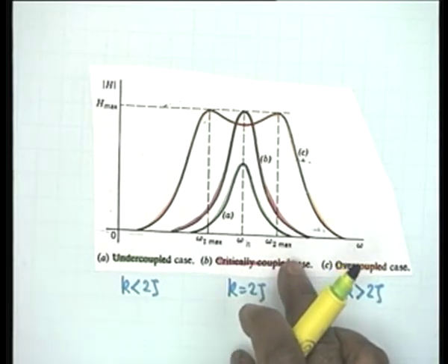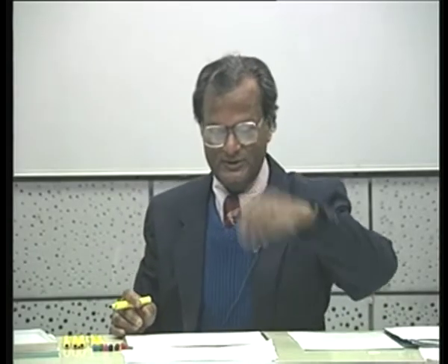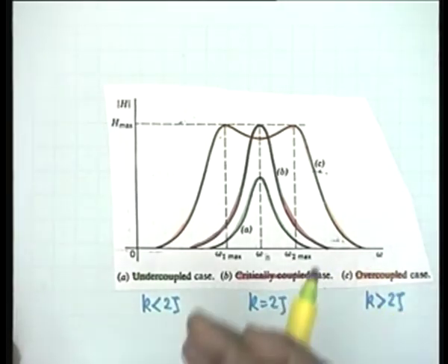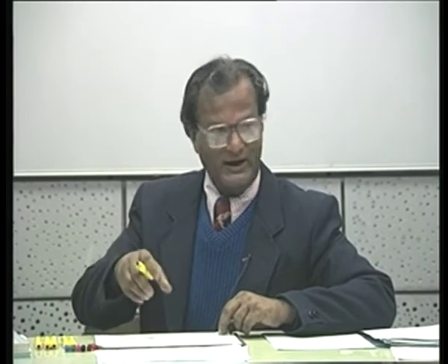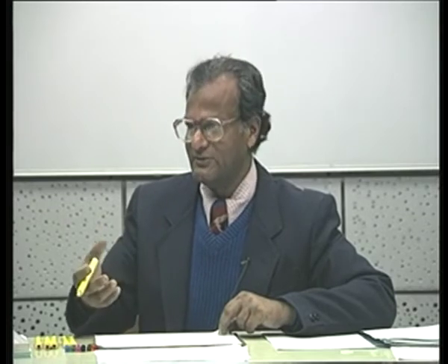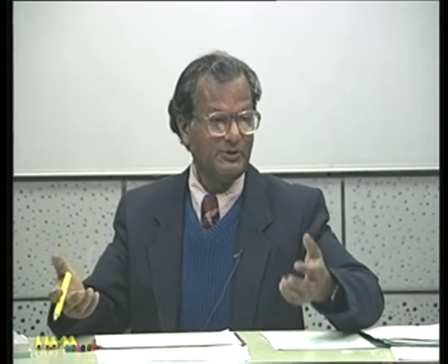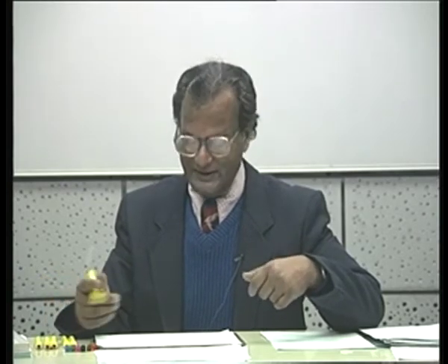Let's find that out. That's a good question. Is there any question about this curve? It can be physically observed. It takes very little hardware to actually carry out the experiment. There are coils in the laboratory. You go to the electronics lab, ask for 2 coils, bring them close together, put identical capacitors in the circuit. Don't use any external resistance, because the coil resistance is enough to take care of the capital R, and then you can actually observe this double peaking.